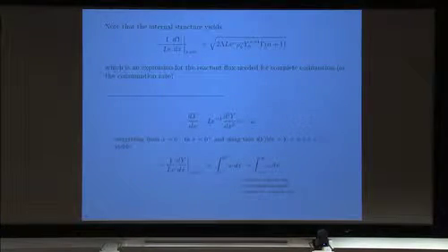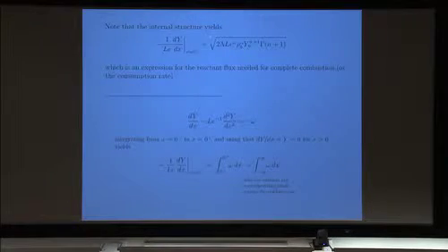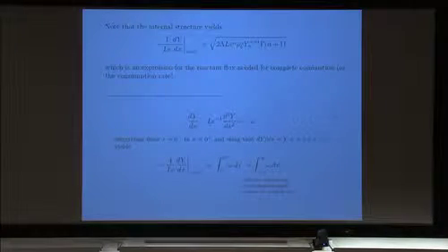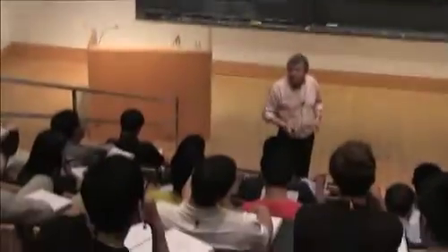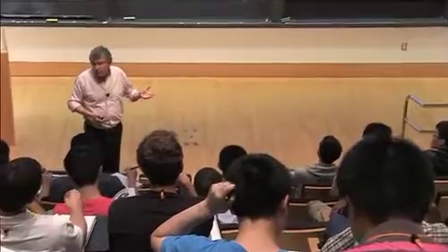For example, the flux of fuel, which is a diffusion flux into the reaction zone, is given by this expression, which has this lambda, and now we know the value of this lambda, okay? And this is actually nothing more than the integral of the reaction rate across the reaction zone. But since the reaction is negligible outside, it's also the integral of the reaction rate across the entire domain, which is sometimes referred to in the literature as a consumption rate or consumption speed.